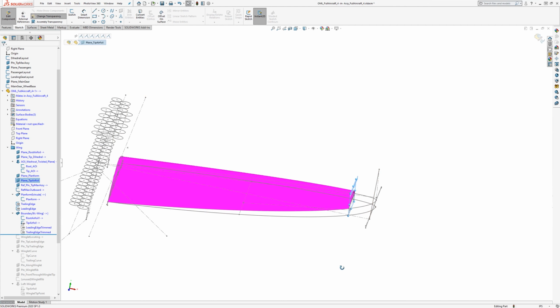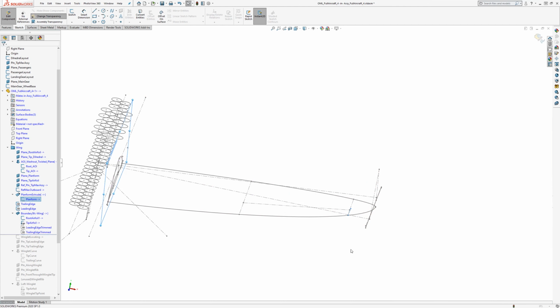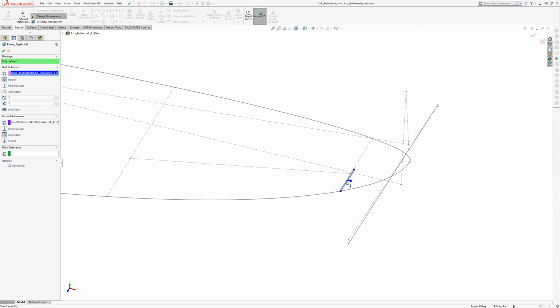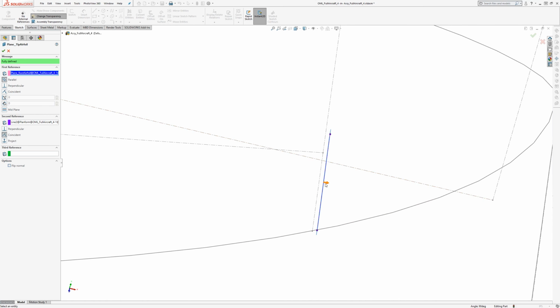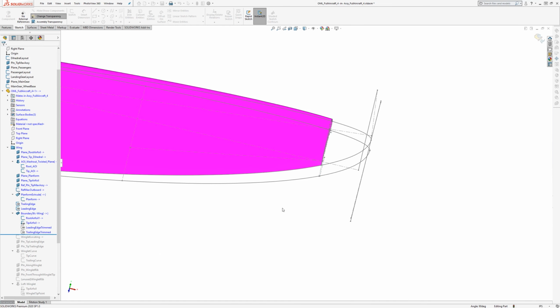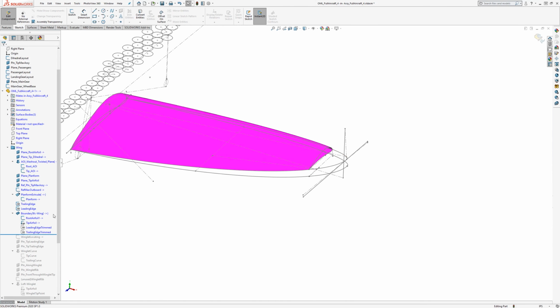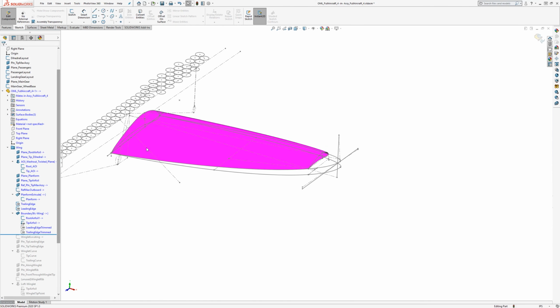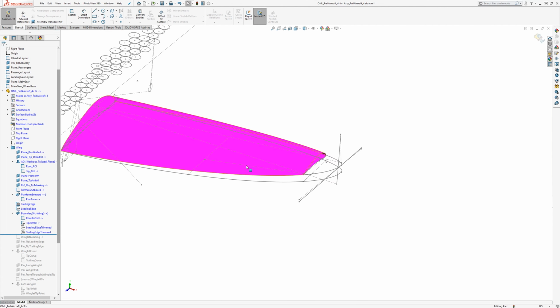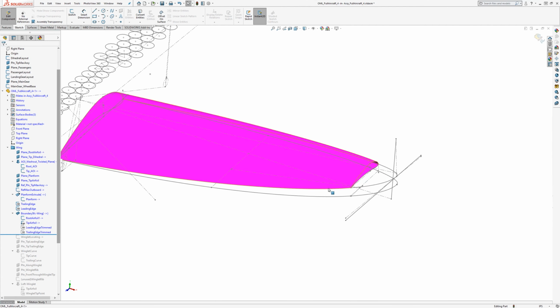This one here just refers to part of the planform, where it knows the aileron ends, and I think it's a quarter of an inch past where the aileron ends. And that's a slightly different airfoil. I think this is the Eppler 422 I used here, and this one is just slightly less cambered. So that's kind of like an aerodynamic washout also.